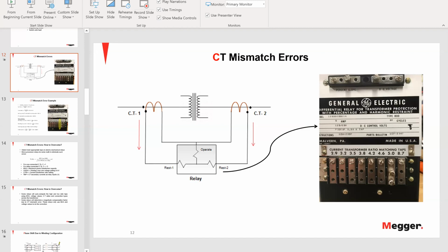It's nothing but a differential protection, but in the zone where you're considering the neutral CTs as well as the phase CTs. Now, the implementation in most of the relays I have seen so far is such that they utilize a directional element for comparing the current in the neutral, which they call the zero sequence current, with the current computed on the phase side. They keep the computed zero sequence current on the phase side as a polarizing current, and then use the current flowing through the neutral CT as the operate current. So there is just a comparison between the polarizing and the neutral, like a directional element.